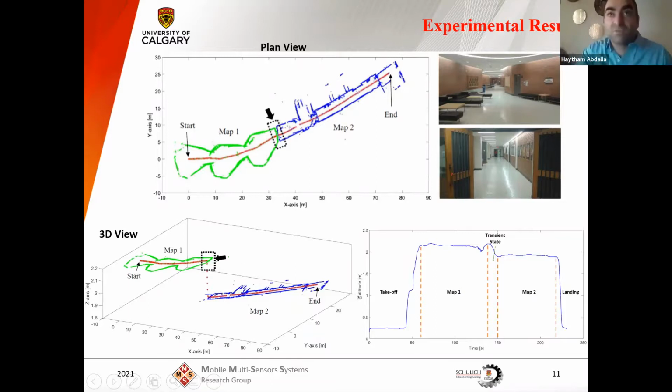So it's an already visited area. And in the new area in front of me, there is an obstacle, and there is no gap in the range of 6 meters. So at this point, the vehicle stops and then goes to the transient state in order to find a new gap.